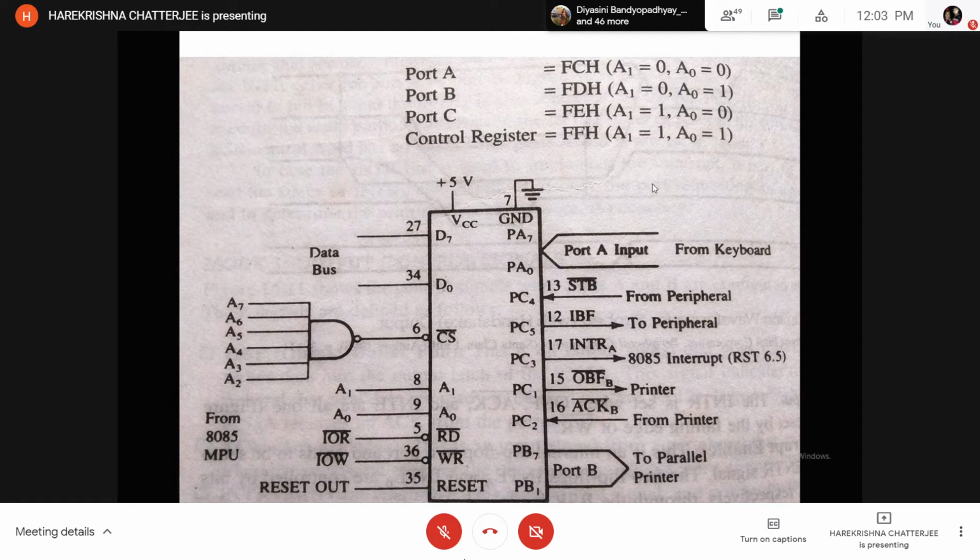The day before, the data ready pin of the ADC, while interfacing directly with the 8085 without using 8255A, was going to generate the interrupt signal to be fed to the 8085. But here 8255A is acting as the buffer chip, avoiding the connection of separate latch or tri-state buffers with IO devices.